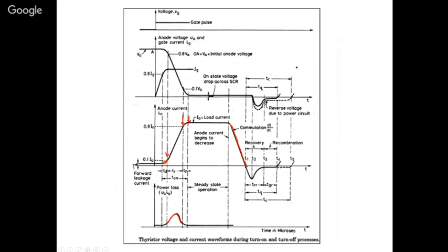So from T1 to T2, around 66% of the whole charge carriers are flushed out. Say when the thyristor is conducting, the electrons are flowing through it. Suddenly you have given a reverse bias, you're turning it off. It will not get turned off at that instant itself, because all these electrons which were there inside have to be flushed out. So from T1 to T2, when you are given a reverse bias, around 66% are flushed out. After that, from T2 to T3, they are flushed out at a faster rate. That rate of change you can see here, it drops at a higher rate.